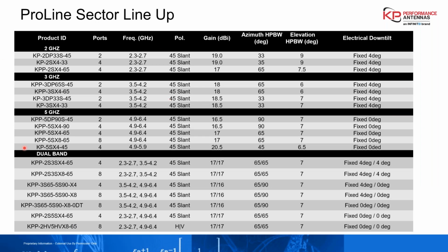And then here's just a big line of the ProLine sector antennas. So what makes a ProLine? Just high level, very stable bandwidth across the entire band. It's got the lifting tow hook on it. We have the universal radio bracket on the mount. Very robust, I would say over-robust brackets on the back now. And very good front to back performance, VSWR, port isolation performance.